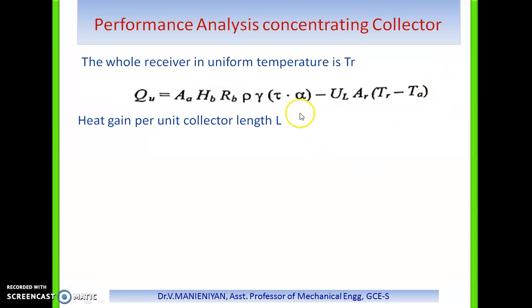A focusing collector differs in thermal behavior compared to the flat plate type because its receiver and shape are widely variable. The temperatures are higher, the edge effect is more significant, the conduction term is very high, and the radiation flux is also not uniform. Therefore, it is not possible to present a single method for estimating the thermal losses. However, the main feature of the trough collectors is considered with a representative parabolic cylindrical reflector with an uncovered receiver.